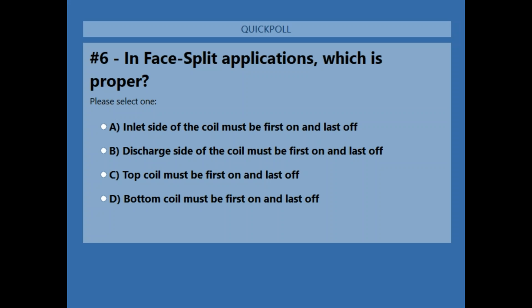No, it's good. Mark asks, can you use 1 filter dryer ahead of the solenoid in lieu of 2 after? Sure. That's the shortest answer you've ever given on anything I've ever asked you, Doug. Yeah, I know. Okay. Yeah, you can do that. You can use a single one. You don't have to have one for each evaporator or circuit. All right.